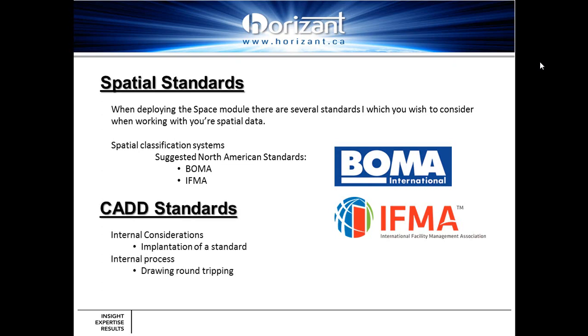At this point in time, it's good to introduce another conversation that we get quite frequently, which is other standards you have to worry about when dealing with your AutoCAD drawings. Some internal considerations you might want to consider is a CAD standard. Maybe you start coming up with a universal CAD standard if you don't already have one, and depicting each one of those different items. This is not a requirement of ARCHIBUS, but it's something you might want to consider when cleaning up and standardizing your drawings, to come up with some sort of documentation on hand so that if you get another drawing as an as-built, you know what standards to follow as part of that process.